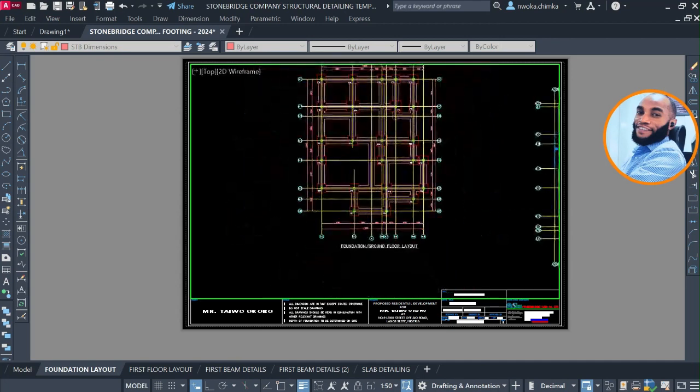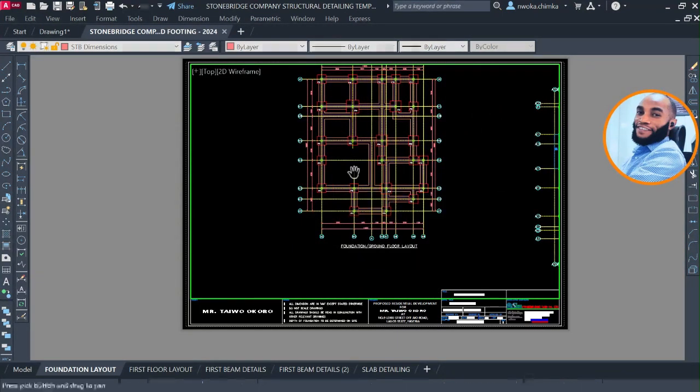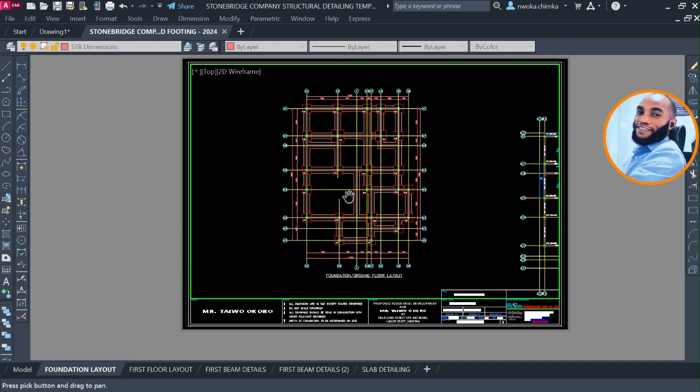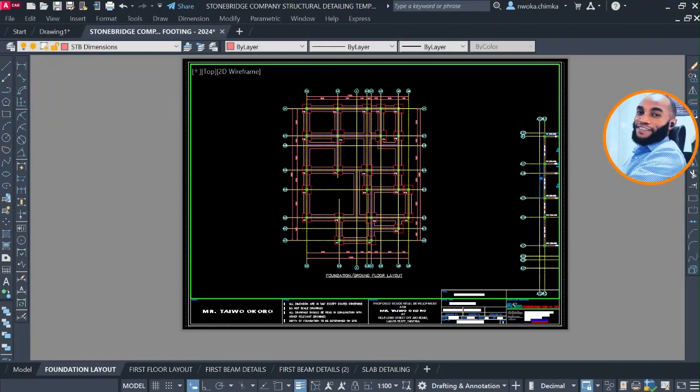Okay, you can now see that 100 is looking a bit good, like I said, but I think there is still some space around this area here. So let me try 1 to 75. I'll press Z, enter, 1 over 75, then press SP, and press enter.